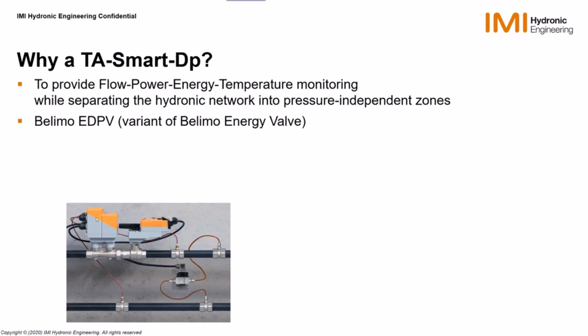And you can see an illustration from one of the documents of Belimo where you see the energy valve, the local temperature sensor, the remote temperature sensor, the delta P sensor element, and then one more temperature body for taking the P1 pressure and a fourth one for taking the P2 pressure. That makes a lot of plumbing clearly here, huh? But we are going to speak about that.